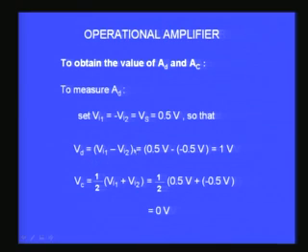So, it is 0.5 volts plus and 0.5 volts minus, and therefore, what will be my VD? VD is VI1 minus VI2, 0.5 volts minus minus 0.5 volts, that is equal to 1 volt. And what is my VC? VC is half of VI1 plus VI2, the average of the two inputs, half of 0.5 plus minus 0.5, and this becomes 0, and therefore VC is 0.